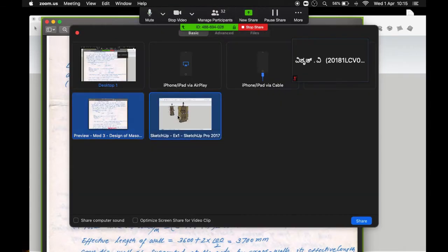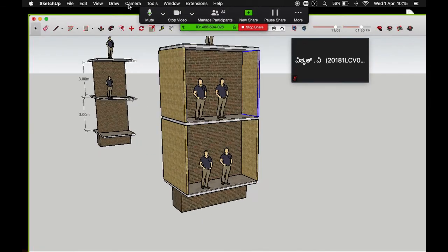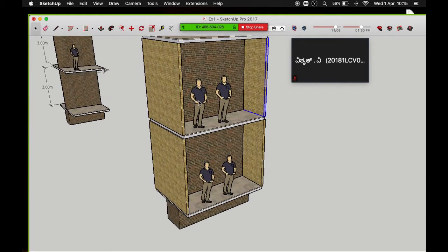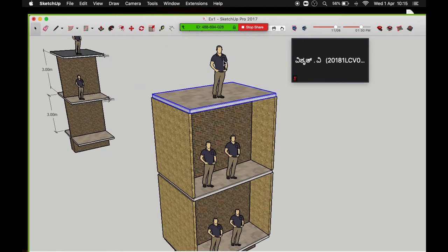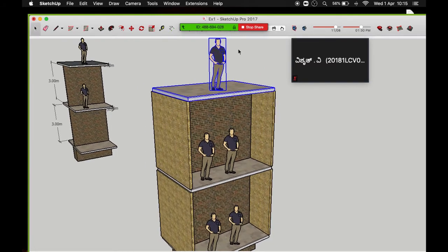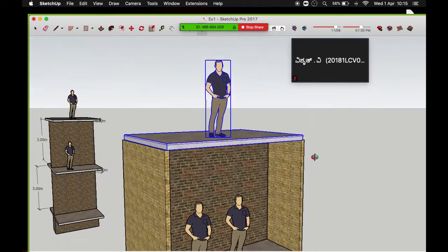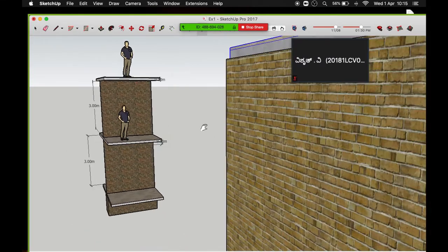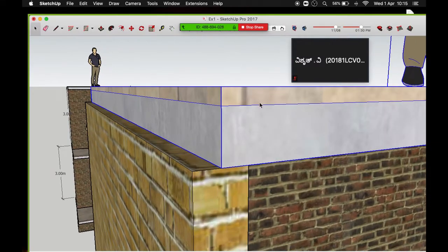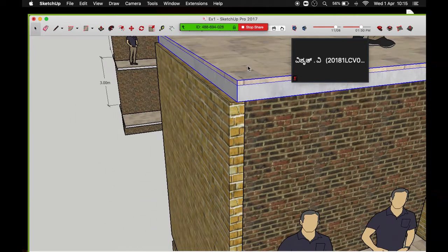Again, this is purely the load from the roof slab. If you see over here, that 5.96 is only by virtue of these two. The highlighted elements in this model are the load of the roof slab. This includes the weight of the slab, which is gray in color over here, and the weight of the 80 mm thick terrace, which is in cream color over here.